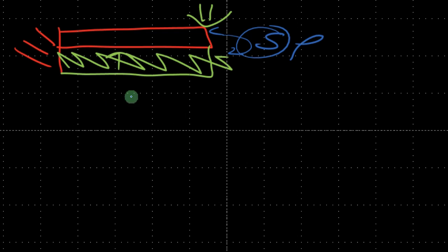In this case, if we draw that stress and strain, again we'll have tension on the top and compressive on the bottom. But the piezo will only see compressive stress, so the net stress the piezo sees is like the average of that. So it's sort of like right here. That's the net force, so the piezo will actually then generate voltage for you. Basically, you have to have the piezo at an off-center position from the moment of inertia in order to get net stress in the material.